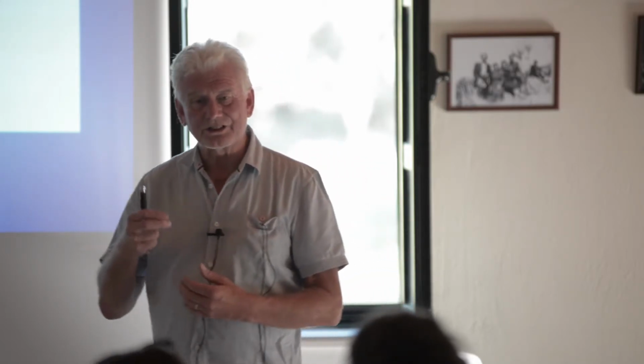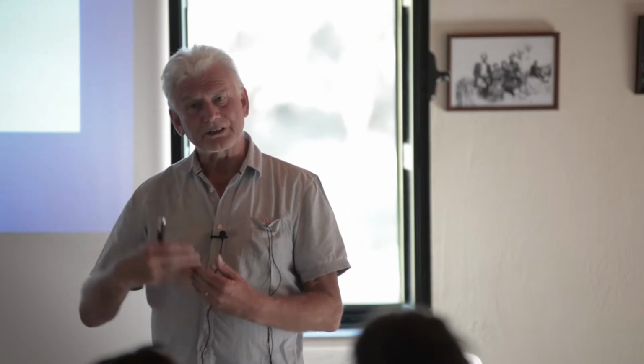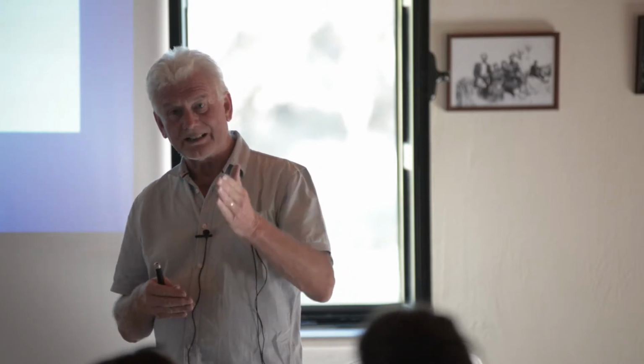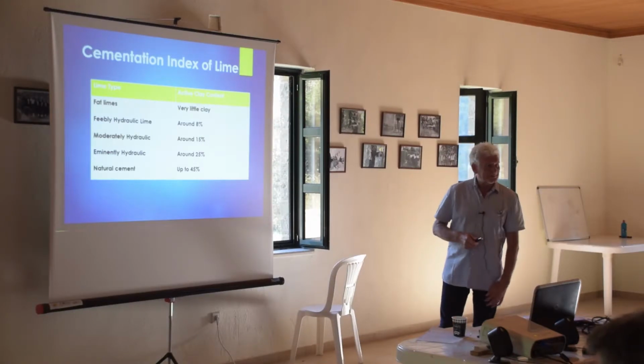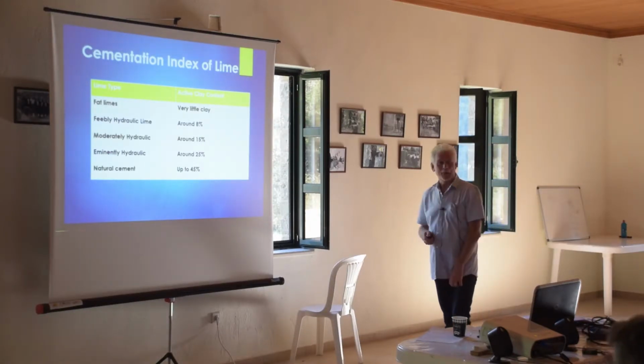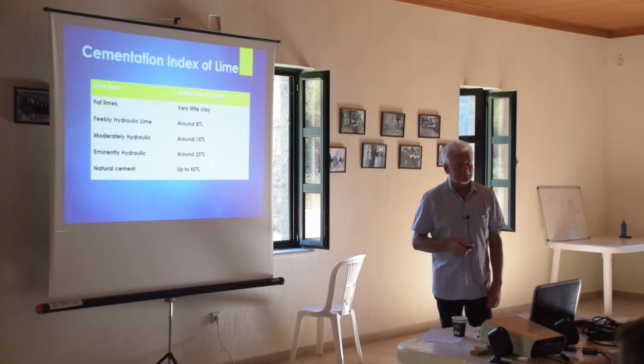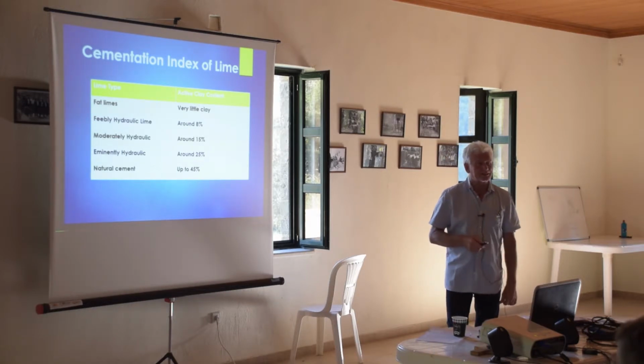Within about 2 days, it had set so hard that when we took it off, it took away the face of the bricks because the bricks were very soft. So we had to redo it. You had to remove it because it was setting too fast? Yes, and it was clear that it was a bad choice.